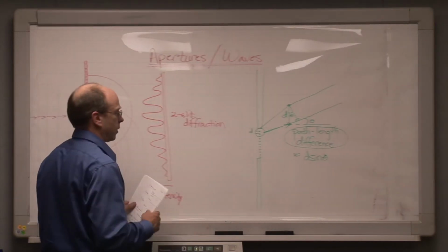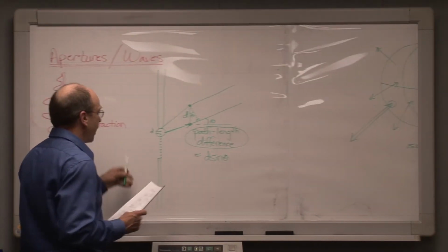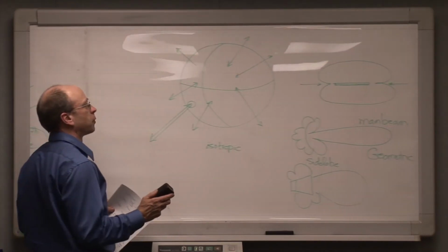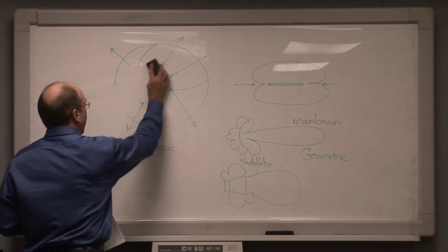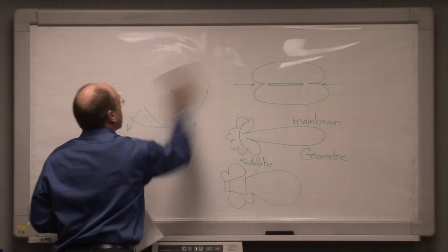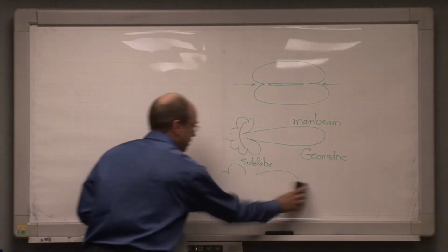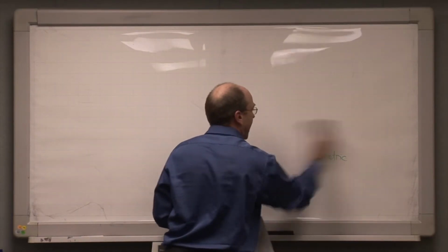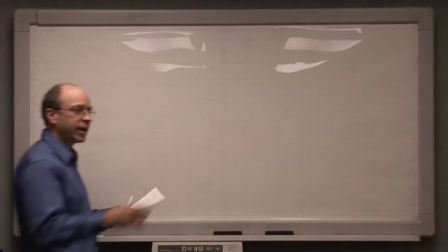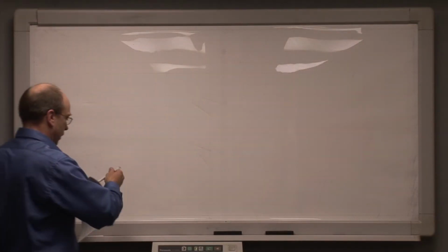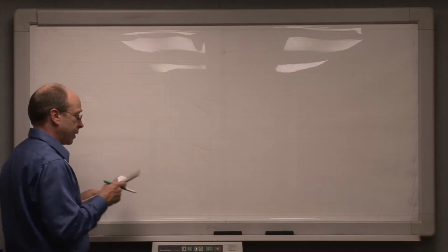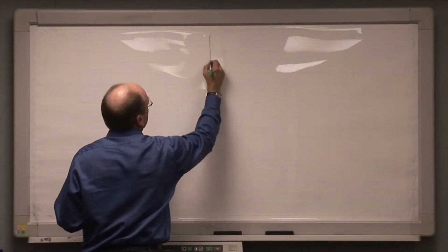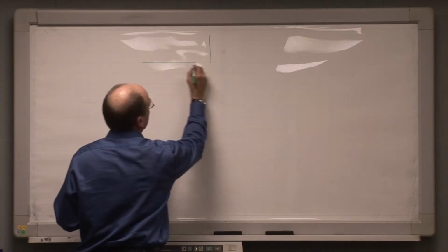Now, as the board rolls forward, imagine that we treat an antenna as if it were a slit with a finite size, like I just drew, which is acting as an aperture for wave radiation. Well, it turns out that that's, number one, a pretty good model. And number two, if we draw diffraction patterns